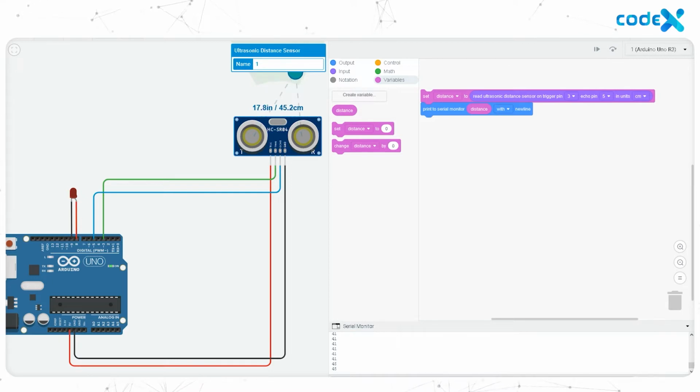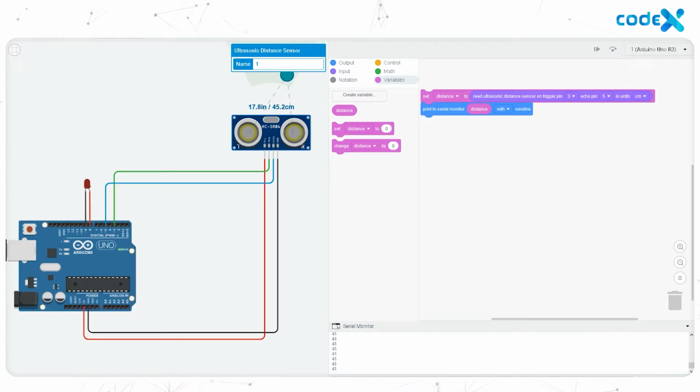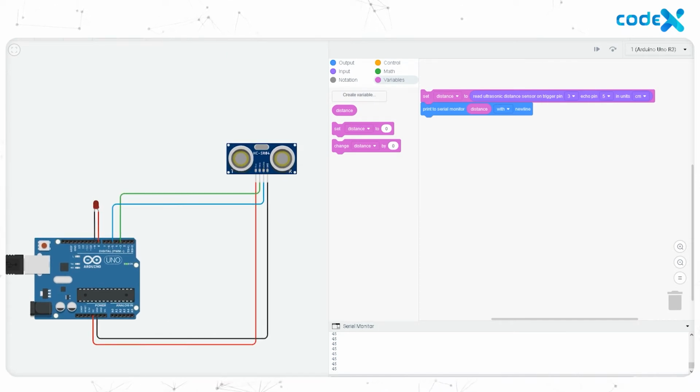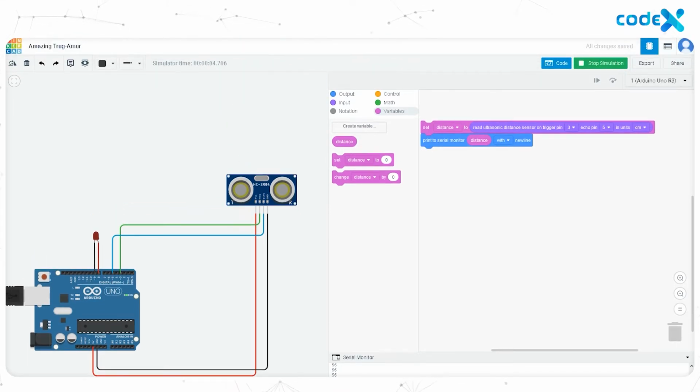on the sensor. Let's zoom out and drag the circuit down to see the range of the sensor more clearly and press the ultrasonic sensor. Move the obstacle again and we can see the change in value. Now stop simulation. Now let's turn an LED on according to the distance between the ultrasonic sensor and obstacle.